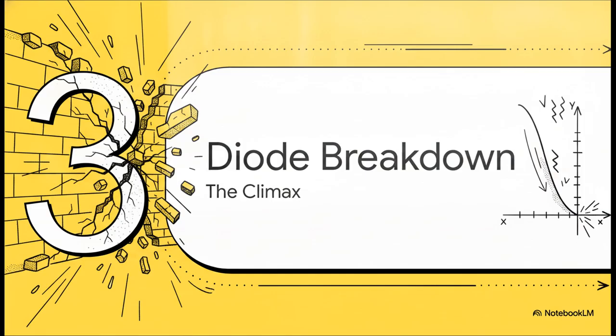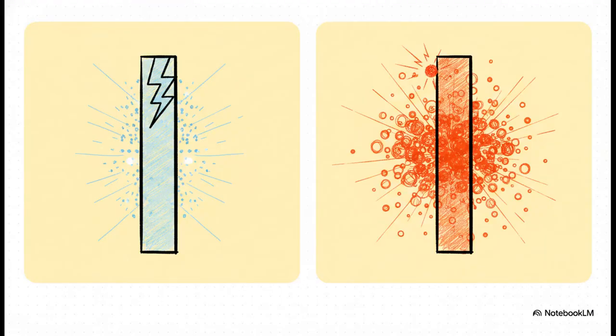Let's look at diode breakdown, the climax. As we know, every wall has its breaking point. If you just keep cranking up that reverse voltage, eventually the electric field across the junction becomes so ridiculously intense that the barricade violently breaks down. And this happens in one of two ways.